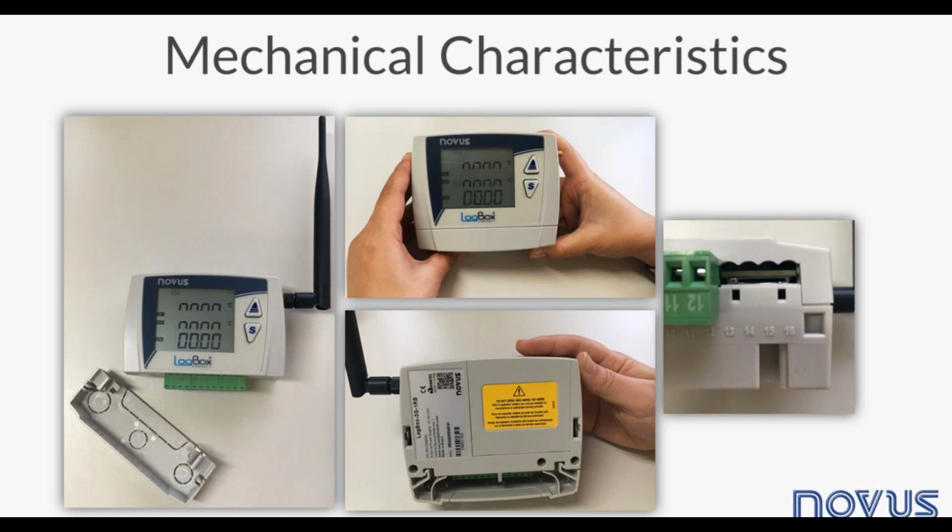Now, in the back part, there is a compartment for the rechargeable battery. The end user cannot open the cover because the replacement of batteries must be carried out by authorized personnel. That's because there is a risk of explosion if the user uses the wrong type of cell. The 3G SIM card holder is placed next to the terminal connector. The holder allows polarized direction and click feature.